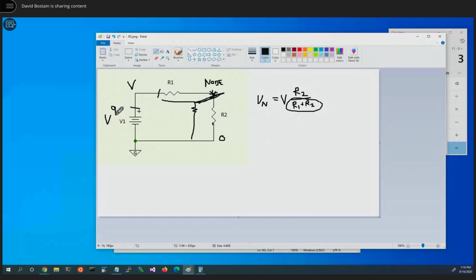So let's say we have 9 volts over here. I think we did this actual problem. And we said this was 100 ohms. And this guy over here was 200 ohms. Well, we can work the problem over here if we look at the entire thing. We say in this case, we're going to take 9 volts. We're going to multiply it times 2, which is the 200 ohms. This is volts. Divided by 200 plus 100, which is 300 ohms.